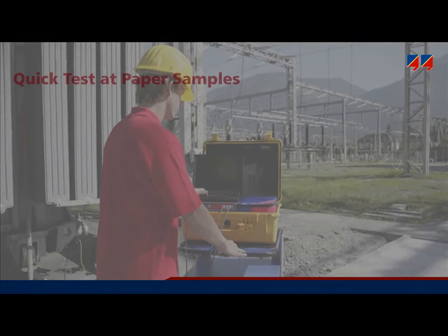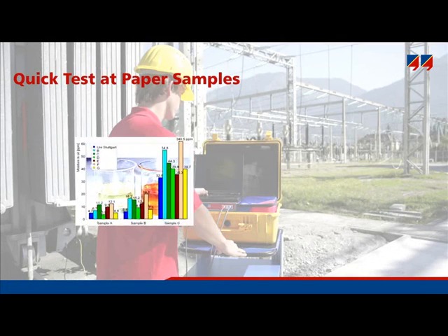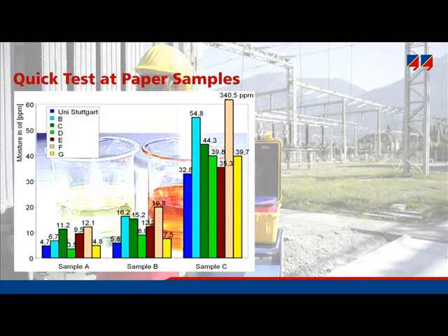The next diagram compares the results of moisture in oil, again done as a round-robin test. 2 samples of new oil and 1 of aged oil were sent to the same 7 laboratories. What did the laboratories find in this case? Here the scattering was even worse. For the dry sample, the results vary between 3 ppm and 12 ppm. For the wet sample, between 35 and 340 ppm.